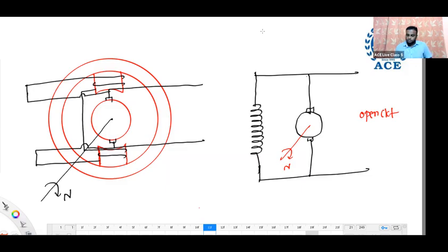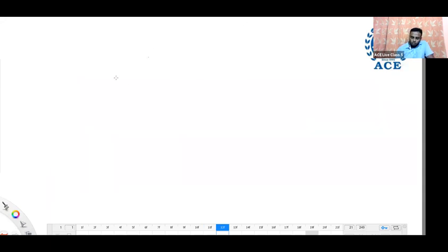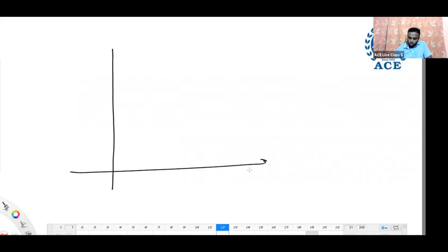Okay, see here. There is no field current here first. No field current in this. Okay, no field current. Observe, this is also no EMF is there. Assume that still it is not rotated. No EMF, no field current in this. When there is EMF, then only a current will flow in this. Okay, so simultaneously I will draw OCC also. OCC also I am drawing. Open circuit characteristics. It is drawn between EMF versus field current, ISH.